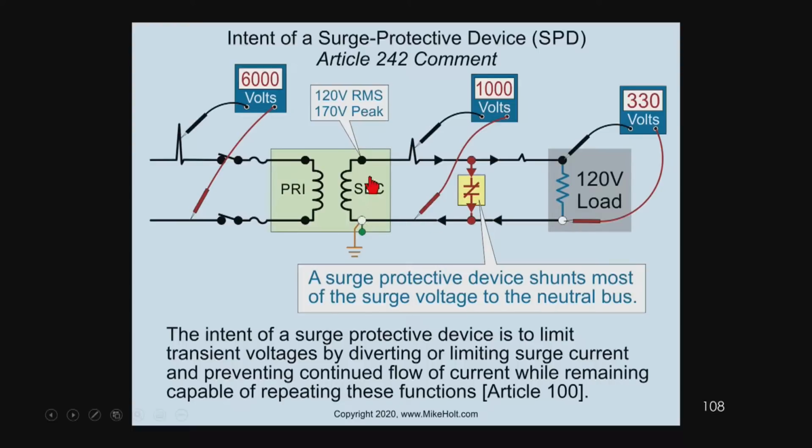So where's the voltage go? Well, it's a series circuit. This might end up being 100 volts on the wire or 200 volts on the wire, or 800 volts on this wire, and this device here, let's make it easy, 1,000. Let's say there's a 100 volt drop across the wire carrying whatever thousands of amps, and a 100 volt drop across this wire. So that's going to get me down to 800, but I need to get down to 330, and then this is going to be, let's say, 470 volt drop across this. So the voltage isn't going anywhere, it's just being distributed.